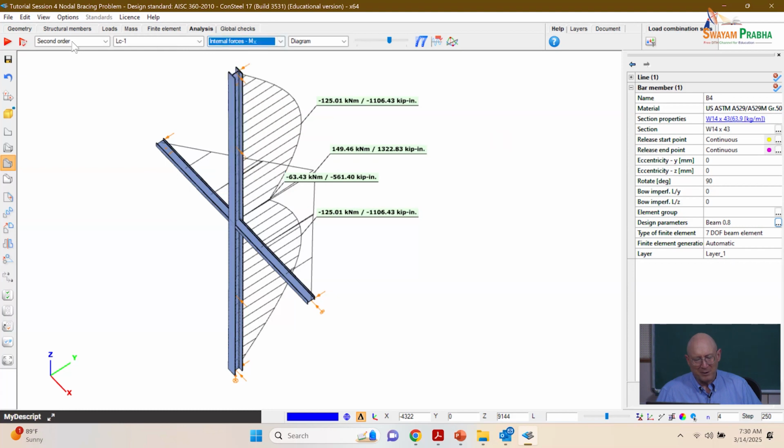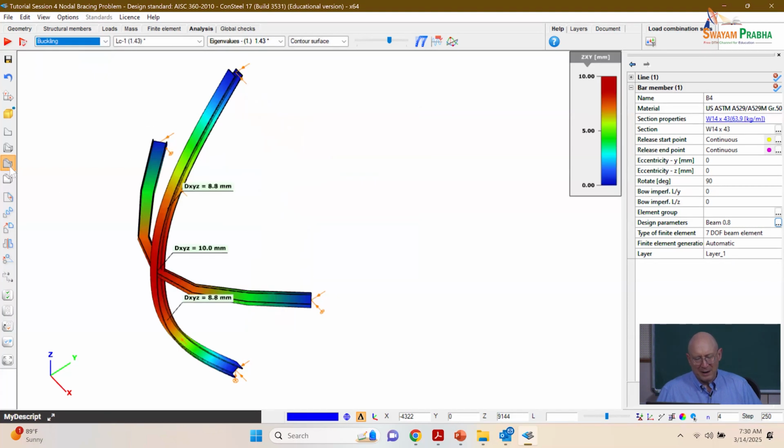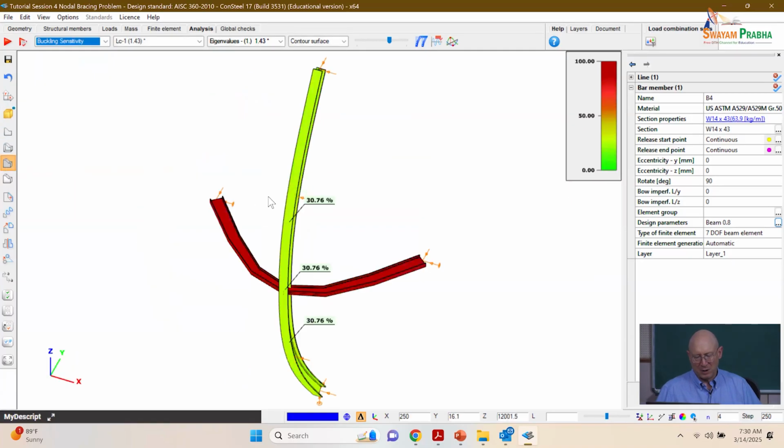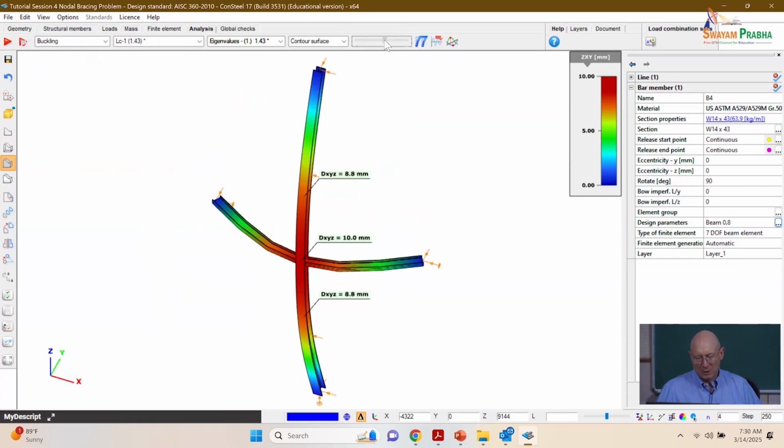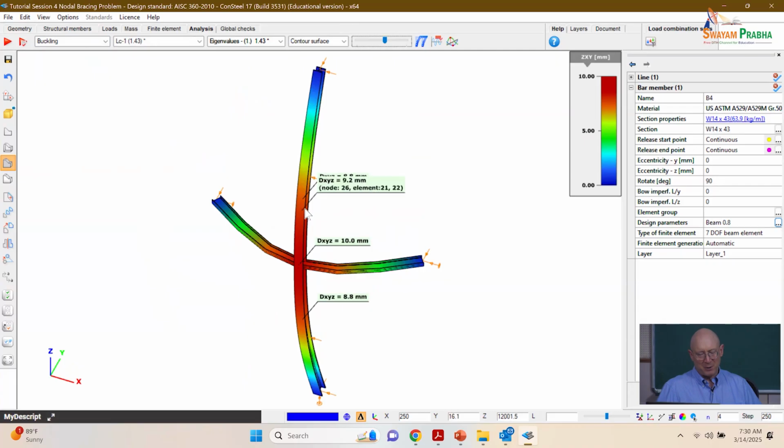If we go to the buckling analysis, let me turn this so that's, okay. Yeah, it's actually buckling toward us. We'll tone down the buckling mode a little bit. The first buckling mode is what we're seeing here with the partial brace, right? We would expect to get some of the largest amplification of the displacements based on the way we put this bow in the column.